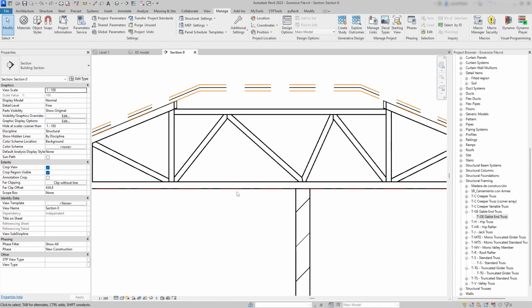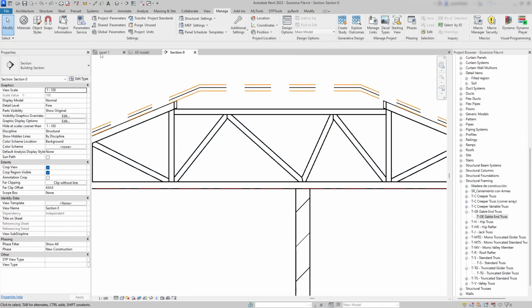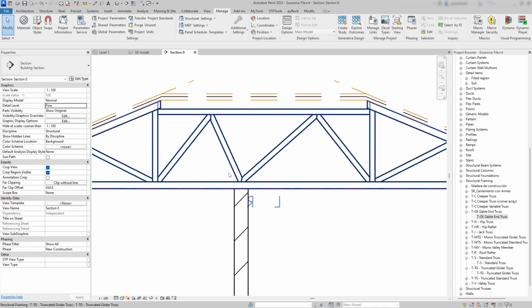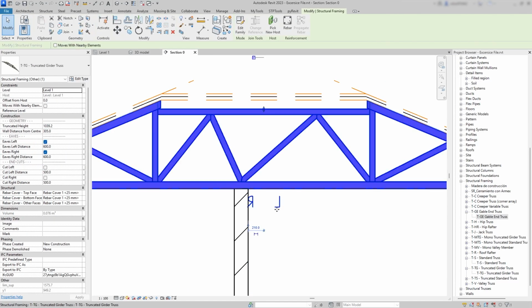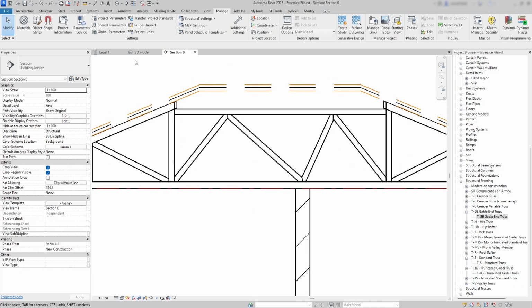At this stage, you may have noticed that when you select the truss, or even just hover over it, Revit shows you labels indicating which side is left and which is right. Even if the section were created facing the opposite direction, you can still clearly identify where the wall is and apply the correct positive or negative value for eccentricity.